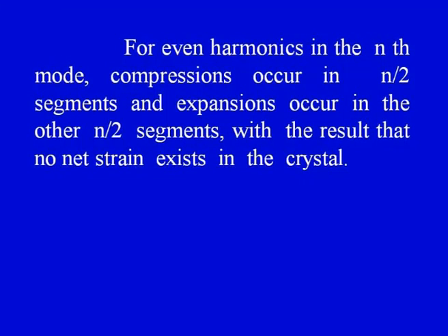For even harmonics in the nth mode, compression occurs in n by 2 segments, expansion occurs in the other n by 2 segments, with the result that there is no net strain, and there will not be any piezoelectric effect.